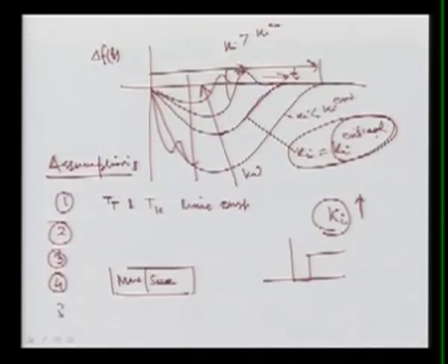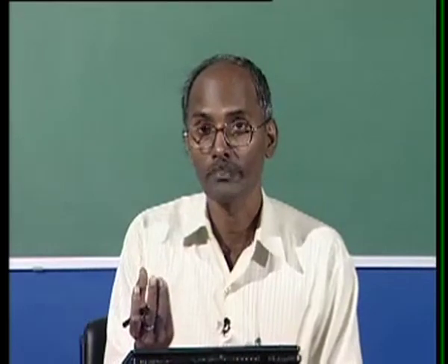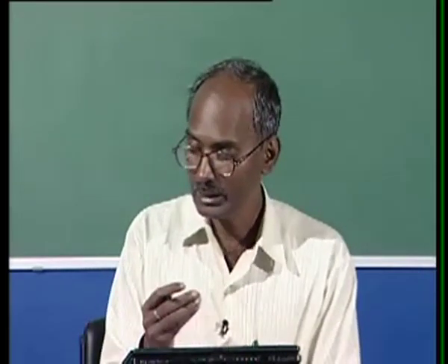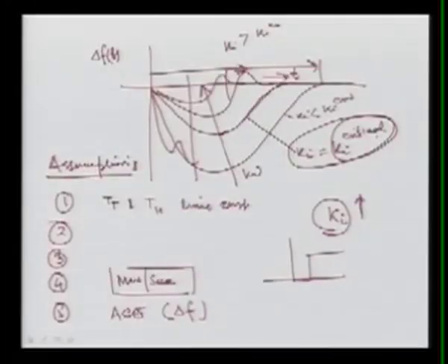Fifth assumption that we made, that is also very important, we have assumed that ACE is available as a continuous signal. This area control error, ACE, is nothing but your change in frequency. We have assumed that it is a continuous signal that we are getting, but it is not so, because we are using some measurement circuits, and those measurement circuits basically depend upon sampled data acquisition. Means we are measuring at certain intervals of time.